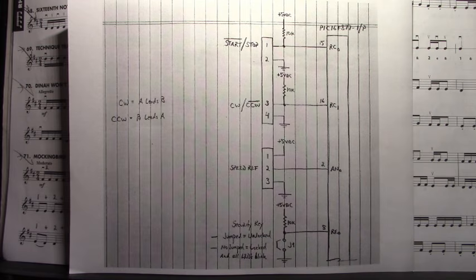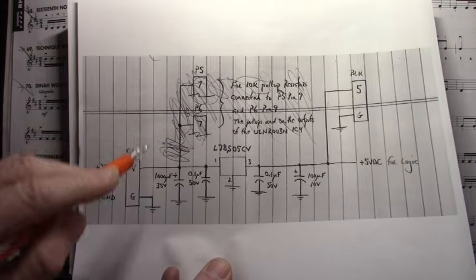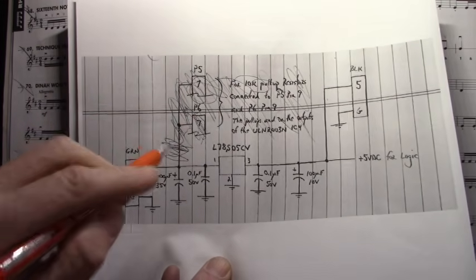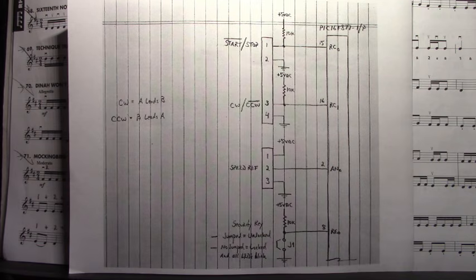I don't want you to have to struggle through this process right here. Okay. Now just remember, let me get this back up here. This is incorrect. This is not correct. The pull-ups are at pin 9 of the P5 and the P6 connector. The Hall effect output and the incremental output for the open collector side, ULN2003A.